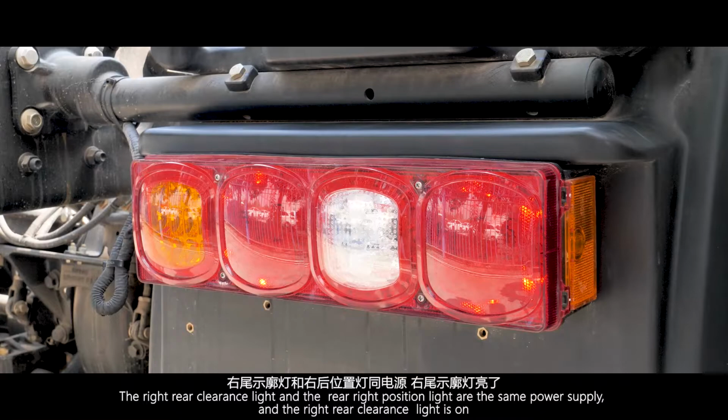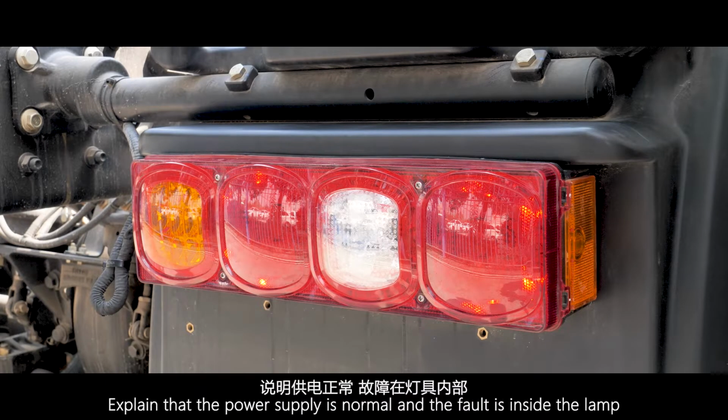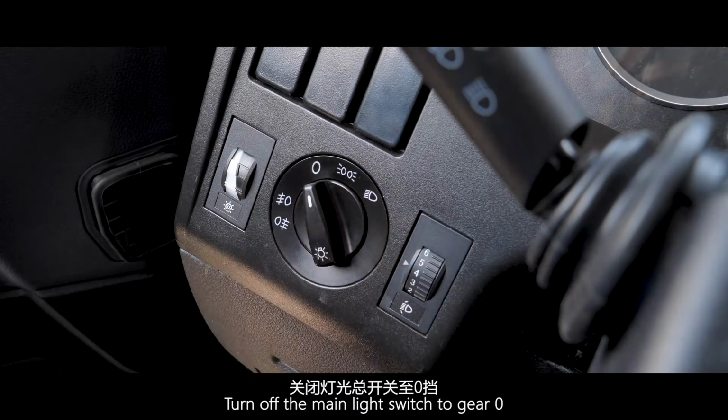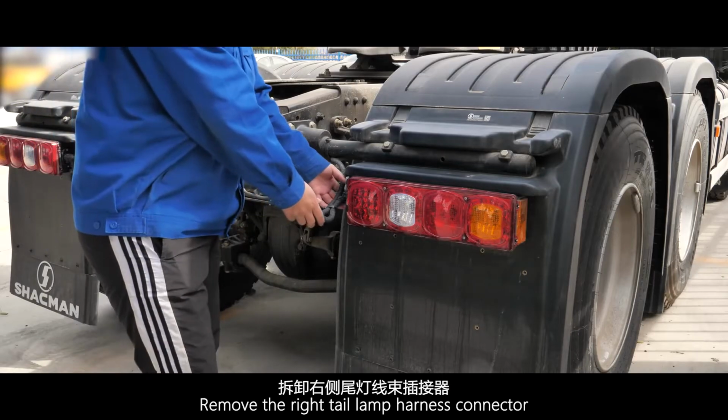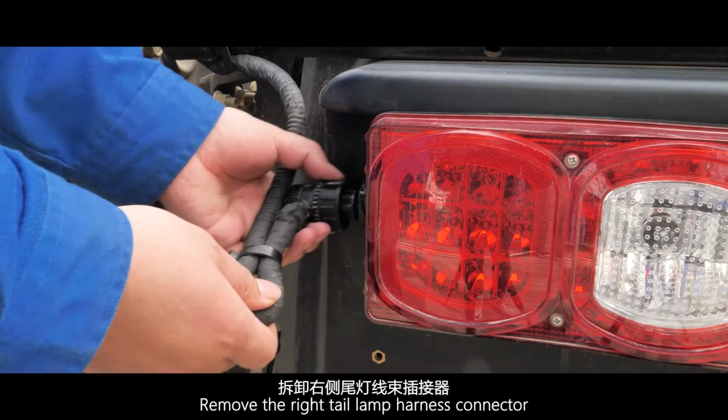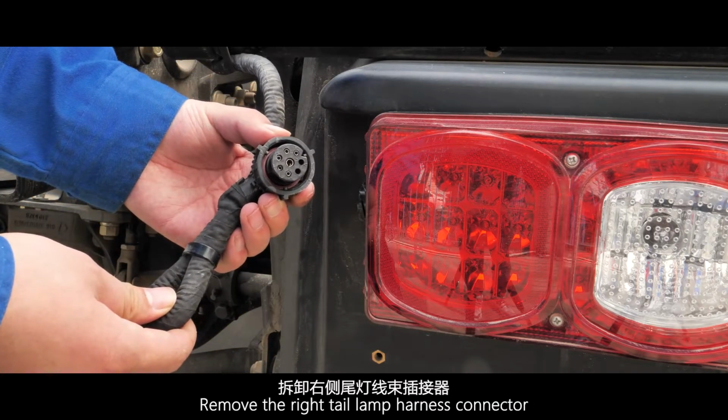The right rear clearance light and the rear right position light are on the same power supply, and the right rear clearance light is on. This explains that the power supply is normal and the fault is inside the lamp. Turn off the main light switch to gear 0. The black probe measures port 1 and the red probe measures port 4.